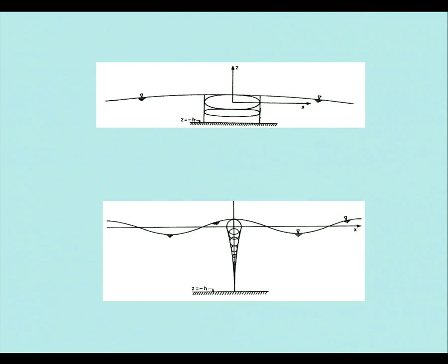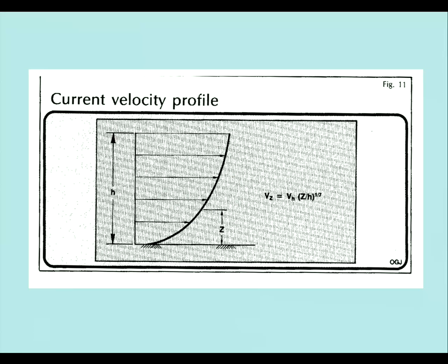So the top of the wave, that's your current. The only way you're measuring current is we put current meters in, a certain height off the seabed. And once we know that height and that velocity that it records, you can then use this law to work out the height Z, top of your pipe, and that's how you work your current out.